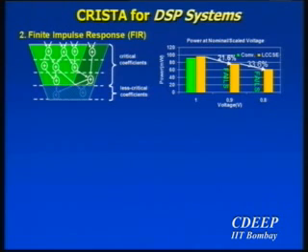It's applicable to FIR filters, right? A simple example of an FIR filter would be a low-pass filter. In a low-pass filter, I know that coefficients C0, C1 are more important than C3, C4. So if I have 100 coefficients, I know which are more important than others. In a band-pass or high-pass filter, I don't exactly know, but I need to do a sensitivity analysis to figure out which are more important than the others.